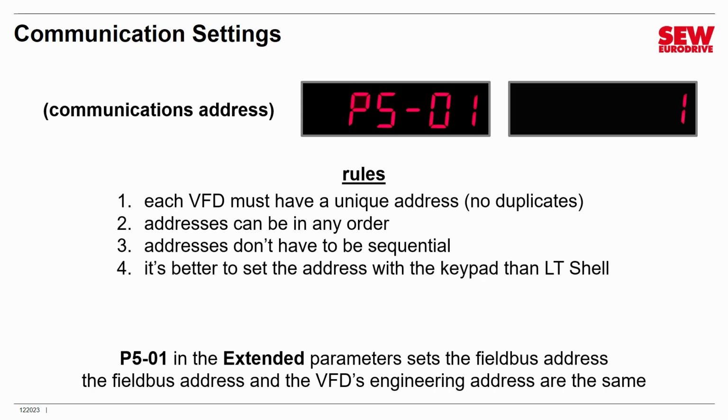And then finally, here's a tip. It's better to set the address with the keypad than LT Shell. The reason is as soon as you change the address in LT Shell, that also changes the engineering address, and you'll lose connection with LT Shell and your VFD as soon as you've changed it. You'll then have to scan back into the network to get reconnected.